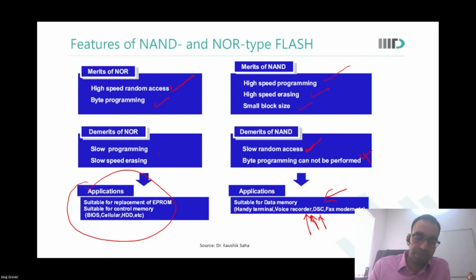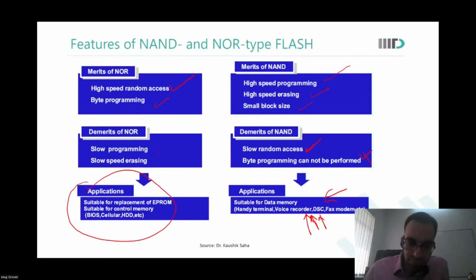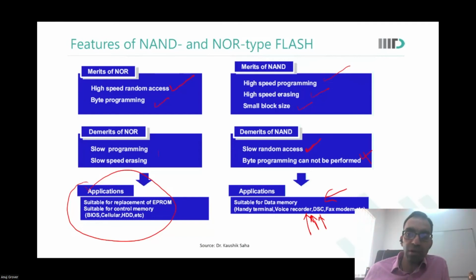Sir, in page register, what will be the mechanism of burst access there? In DRAM, we saw that first we give the row, we do row decoding, and then we give the column address, and we take the burst. But here, how will we do it? So all those schemes that we looked at in DRAM can also be explored to be used here, because they are not linked to the DRAM per se, are they? No, they are all about inter-chip data transfer. So all those schemes you can put over here also, by controlling it.